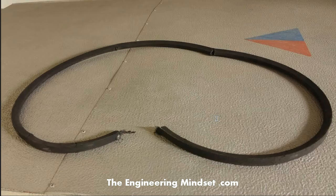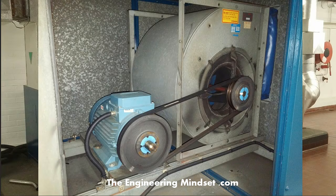If you've got a good control system on the BMS system, it will pick up that sudden loss, that snap, and it will act on that, and it will stop the motor from running. Obviously you should have a good maintenance regime in place to plan preventative maintenance to actually stop this occurring, but it will happen from time to time.